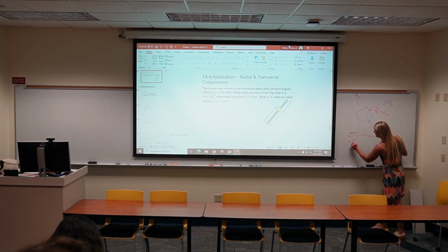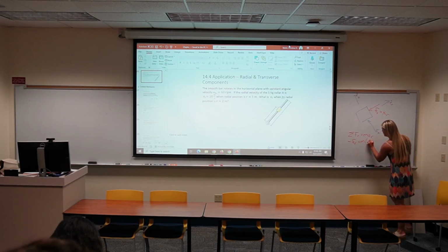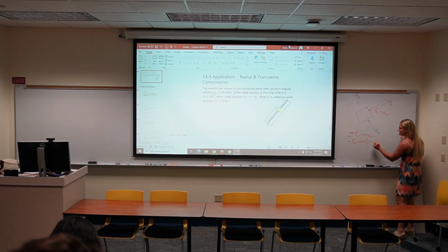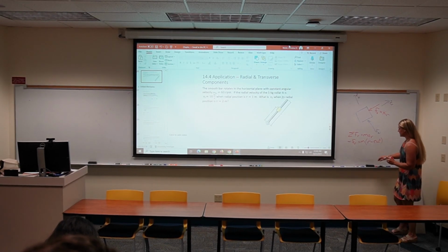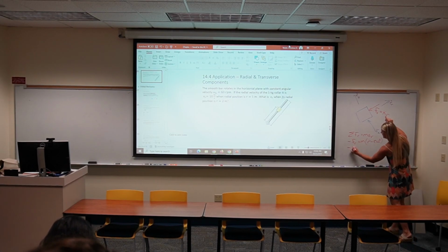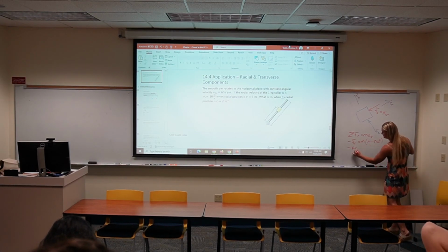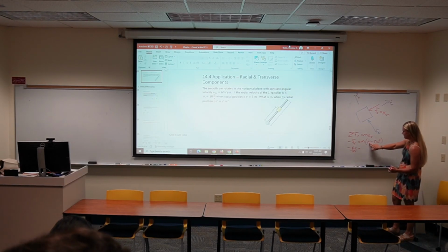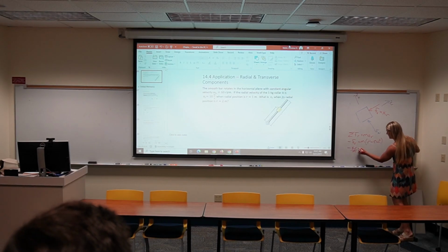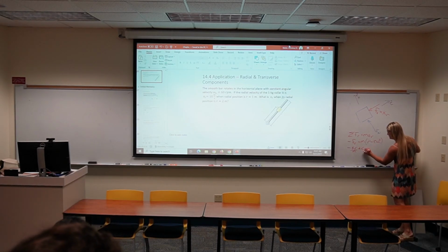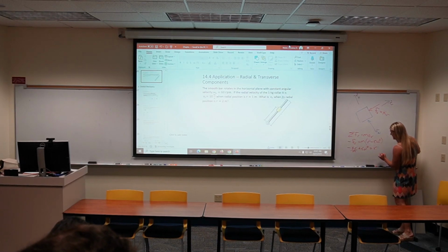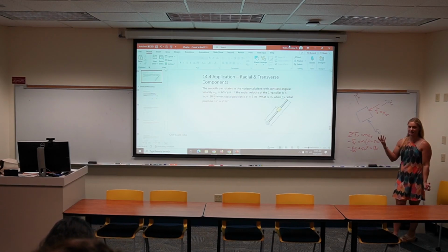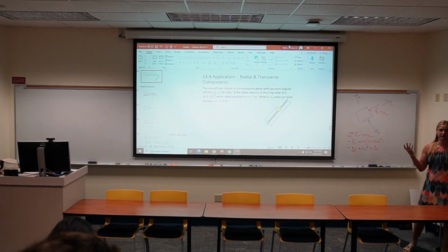So it's going to be negative F_r equals m(r double dot minus r omega squared). Thank you. Good job. Okay, so this is equal to Kr. I'm going to move the m, and I want this by itself, so I'm also going to bring the r omega squared over, which equals r double dot. r double dot is the same as a_r. You plug that into the four-step process, and you can integrate, and you're done.